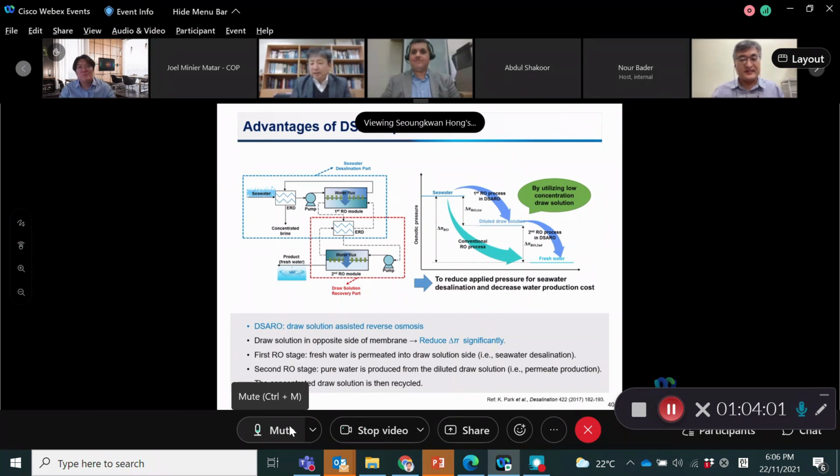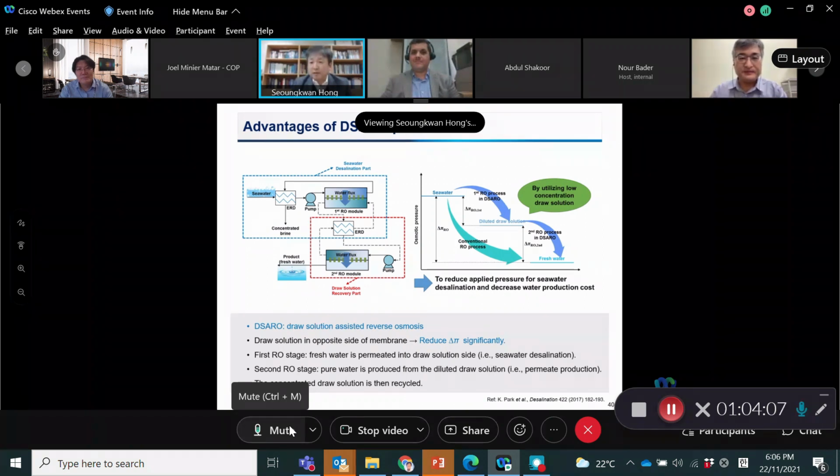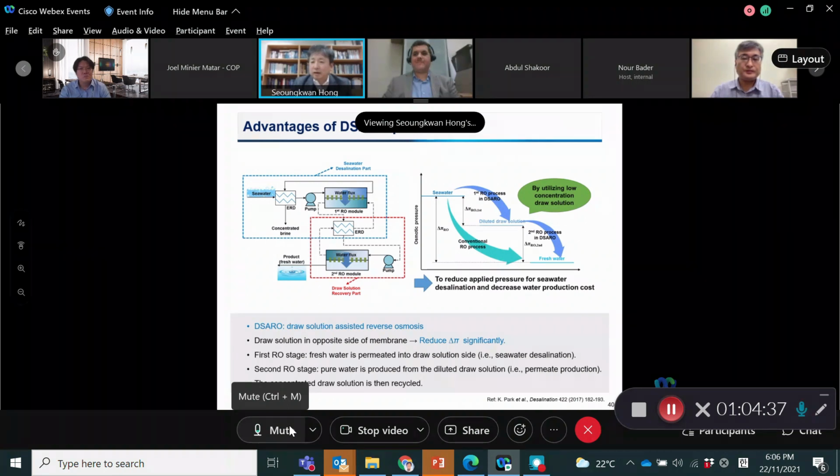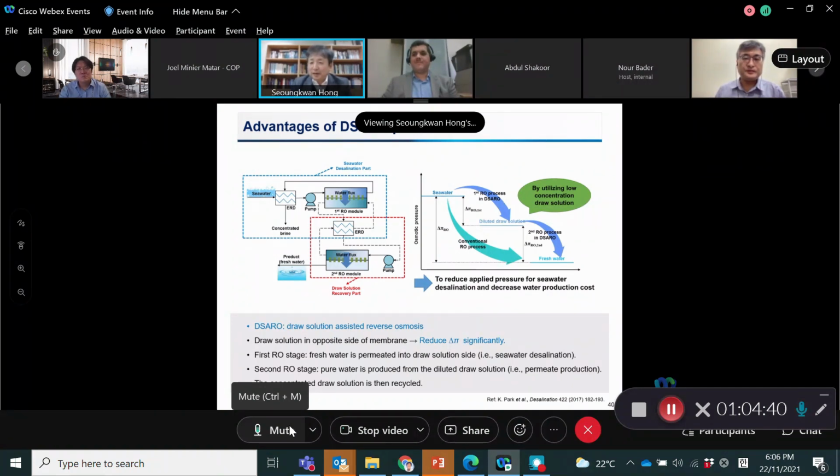To be honest with you, we haven't really tested the possibility of an oil spill in seawater with our developed technology. So I cannot say whether or not the MTF mesh tube filter can actually respond well to this oil spill crisis. That's the reason why DAF is installed in typical SWRO plants, even though we haven't really experienced algal bloom lately.